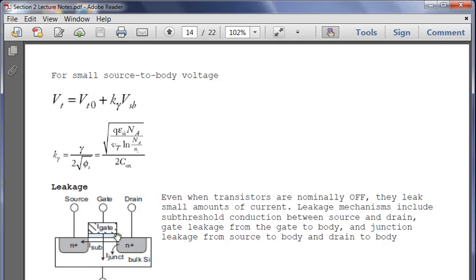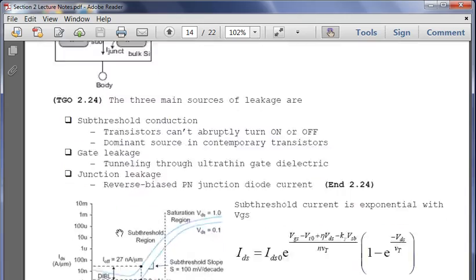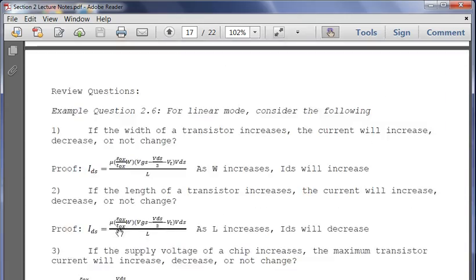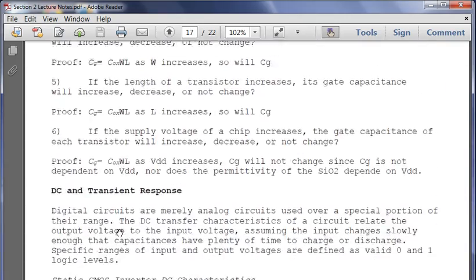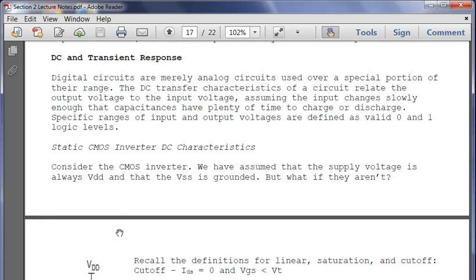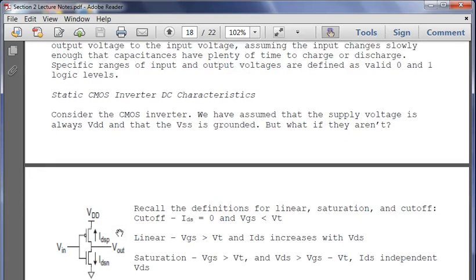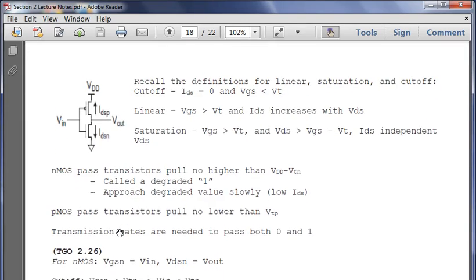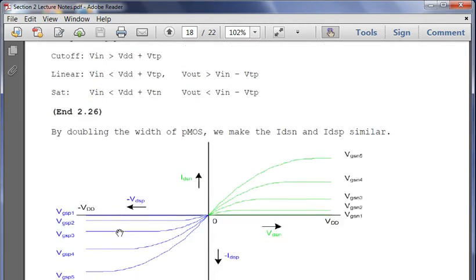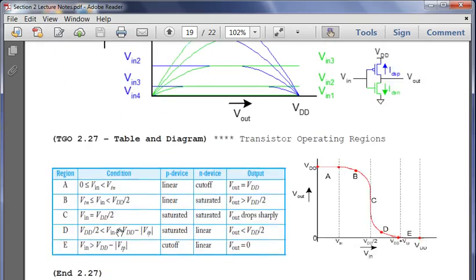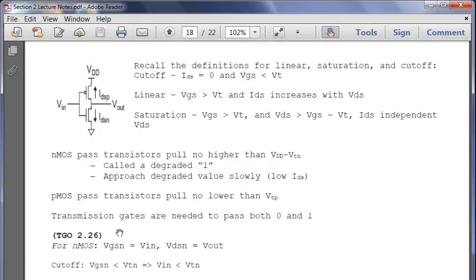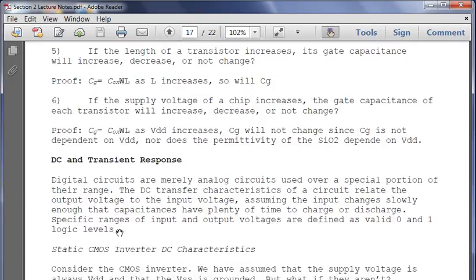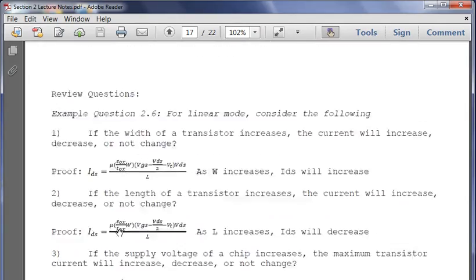So you've created quite the potential here between the gate and the drain, and that's where your gate-induced drain leakage occurs. So then you're creating a significant difference there. The voltage doesn't cause an inversion region, but it does allow current to travel.